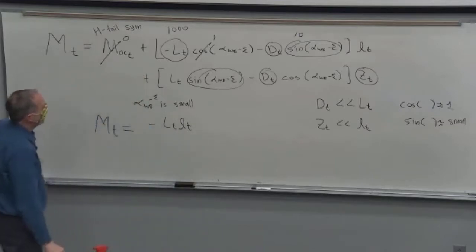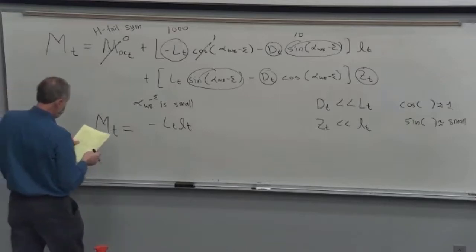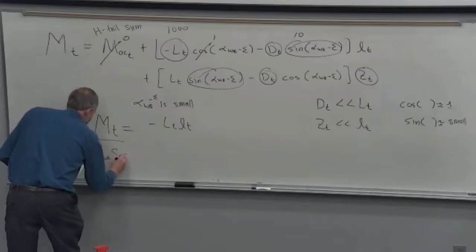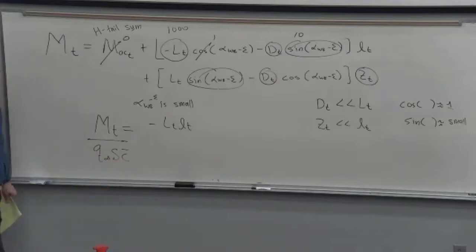But already you can see that if we added this big formula to the big formula for the wing, we'd have all kinds of terms, right? And it would get complicated. And these are legitimate approximations that we can make. All right, so that's pretty easy. And you look at the figure and you could go, yeah, my force and there's my moment arm. So the last thing is we want to turn this into a coefficient. It's for the entire airplane. So we divide by Q infinity S C bar for the airplane.